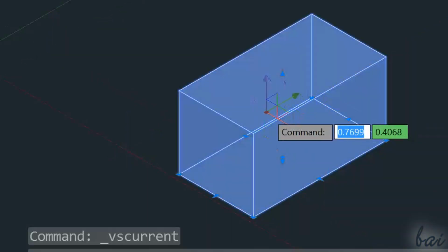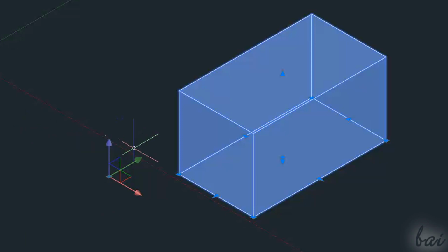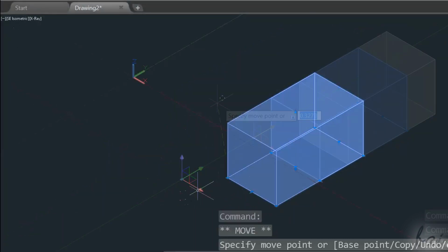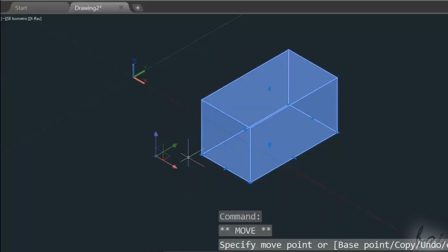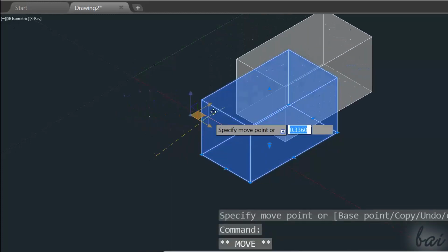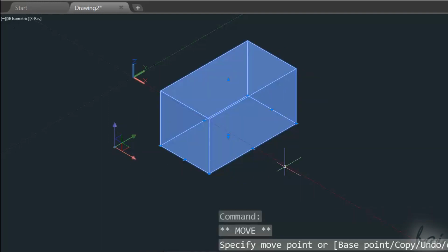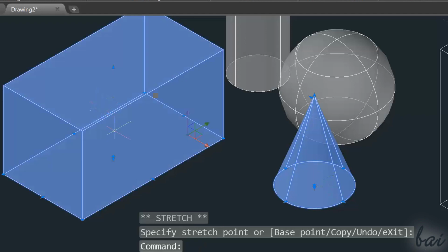Move it by dragging from its central node. If you hover one of the axes, this will be highlighted in orange. You can click and drag to move the selected object, following such axis only. You can also hover a plane to move through such plane only. This tool is very important if you want to align objects. This gizmo appears also in groups of selected objects, of course.